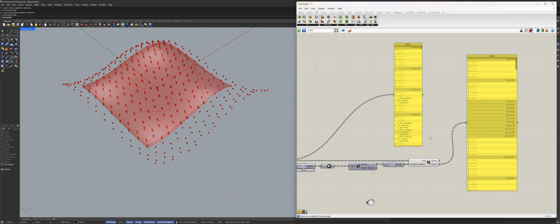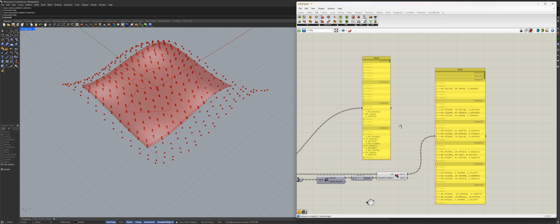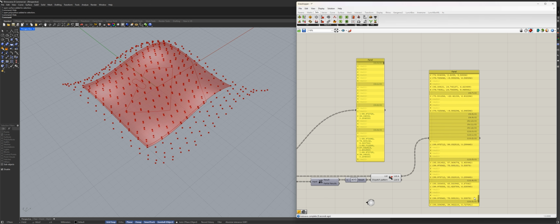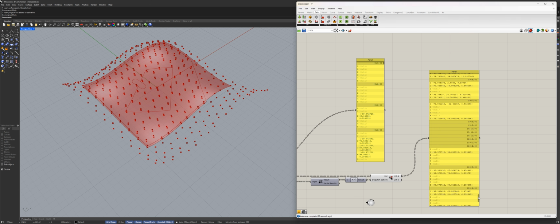And once again, the branches are still intact, they are still there, meaning that I actually can merge that together. If I use a merge command, I can merge list A and B and get where I started. I don't want that. I need a list A. What's more importantly, I don't even need these empties. I want them to go away. There is no data anymore. Please remove that.